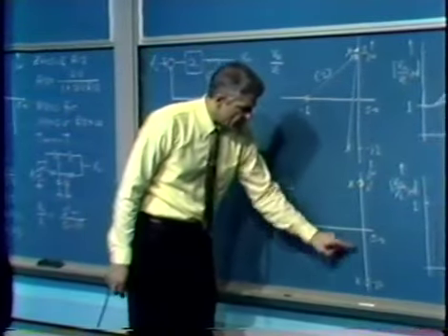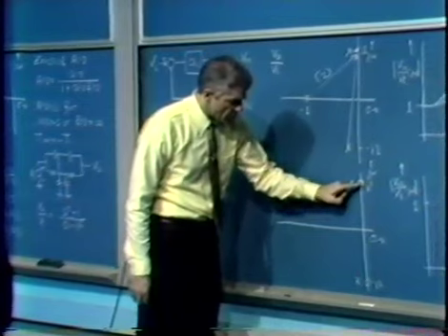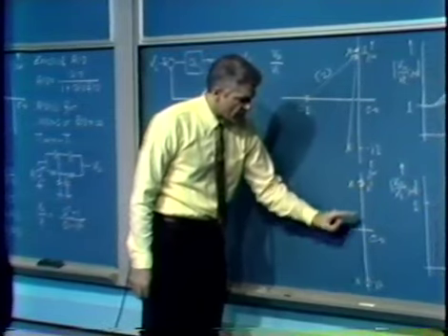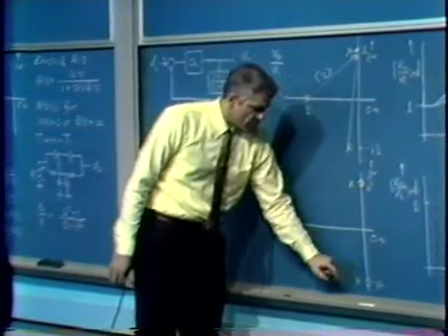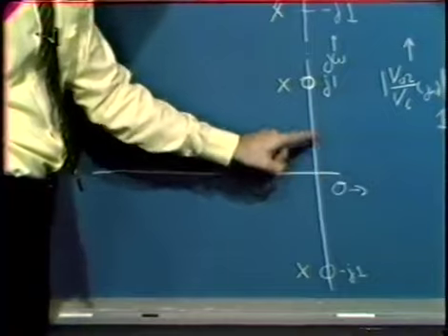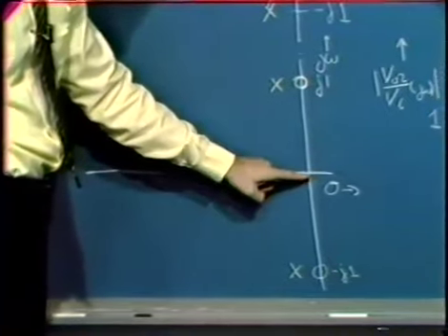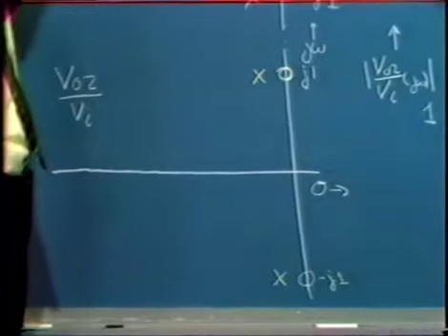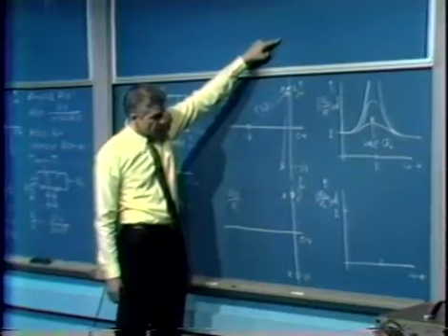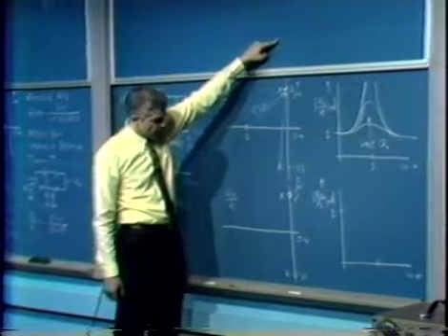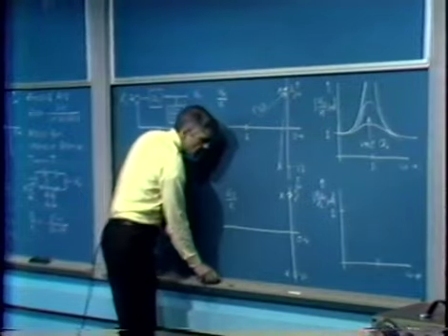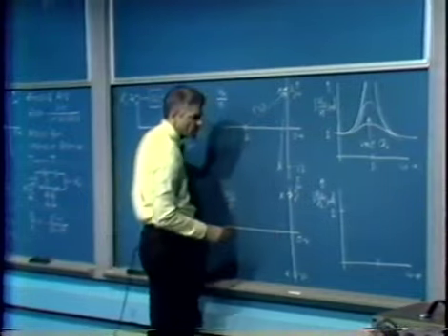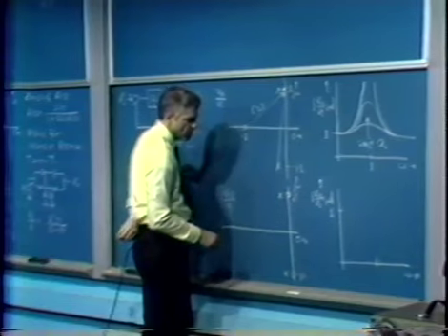We get the complex conjugate pole pair, and the zeros associated with that closed-loop transfer function are those of the T. Again, at DC, the vectors from the poles and the zeros tend to cancel. At very high frequencies, when we evaluate this transfer function for sinusoidal steady-state response, again, the vector lengths cancel. And the only difference occurs again at points near the location of the pole and zero pair.